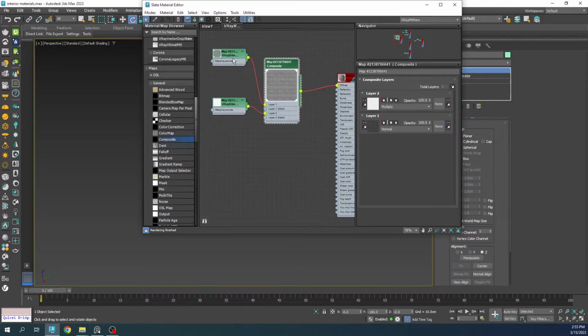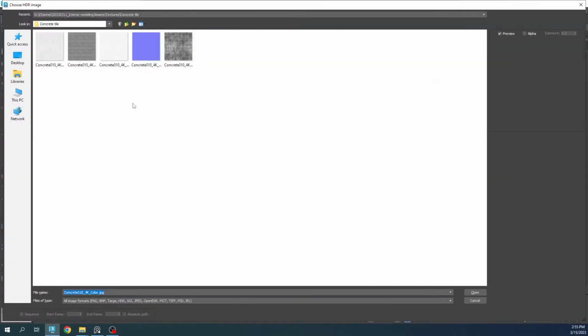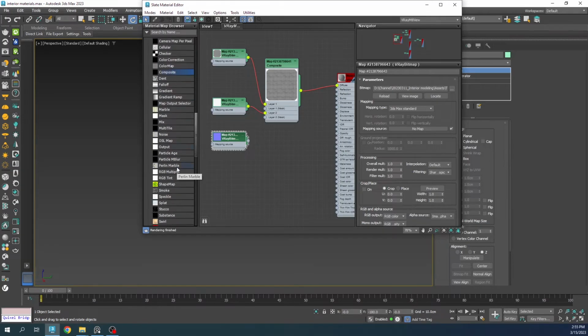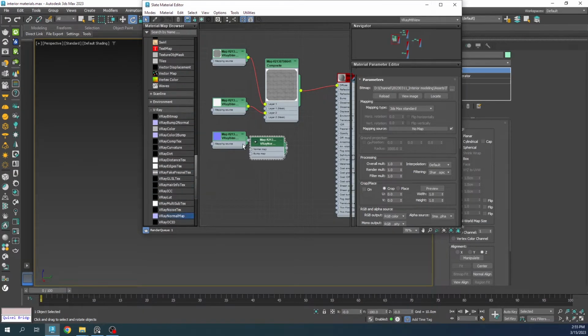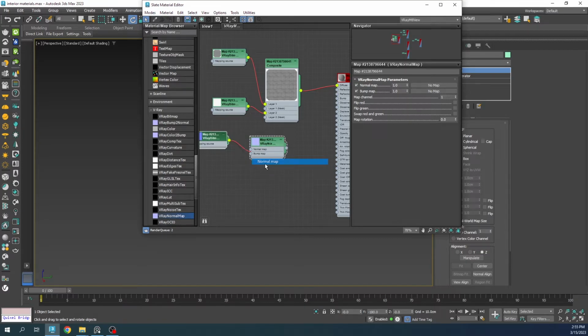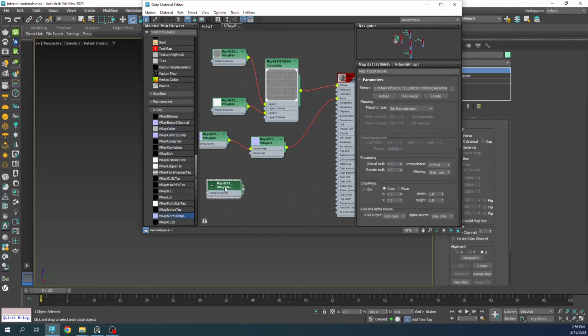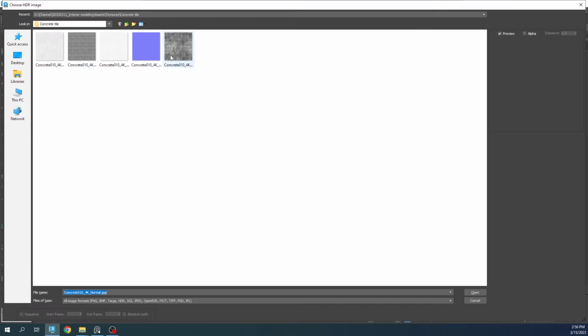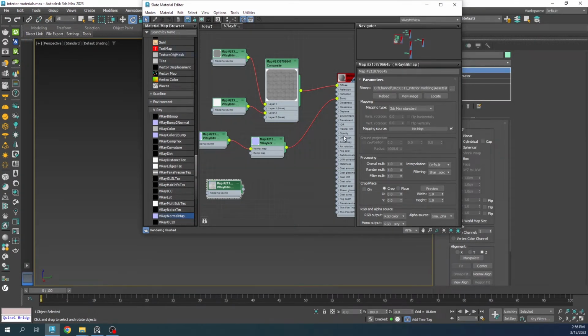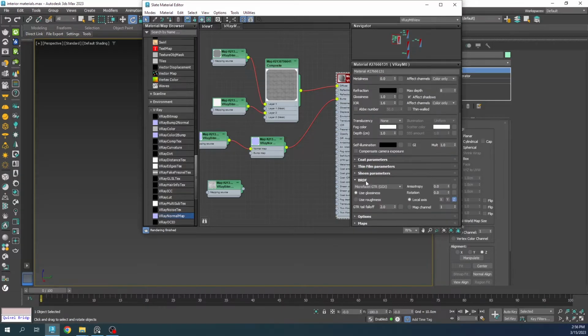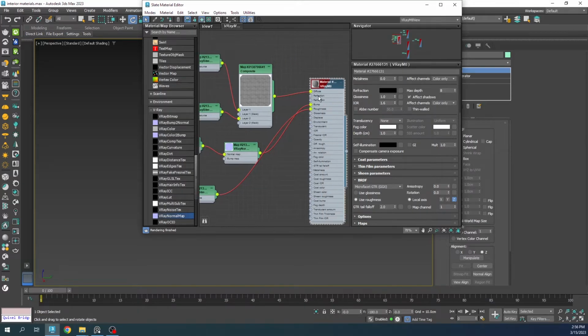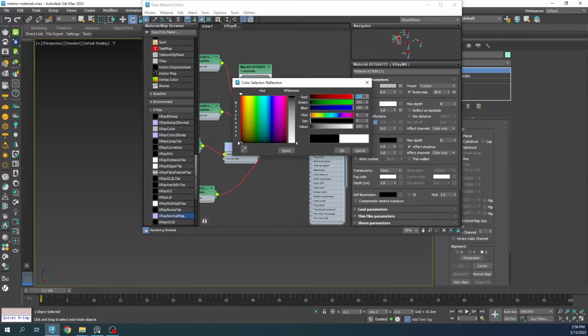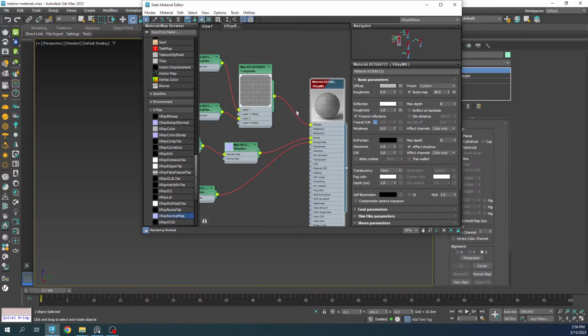So let's make a copy out of this texture as we did for the previous materials and load the other textures. I'm not going to use the displacement, but let's use the normal map. And as I told you before, we need a V-Ray normal map. Let's plug it to the first one and use it as the bump node. Now we need another copy for the glossiness or the roughness map. Okay. And let's go to the VRDF rollout and use roughness and just plug it to this slot right here. We still need to turn the reflections to white, and there we have the material.